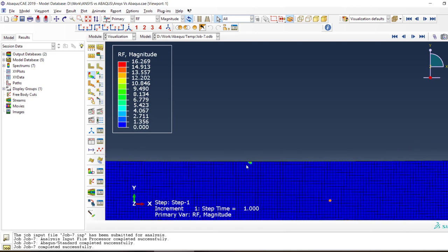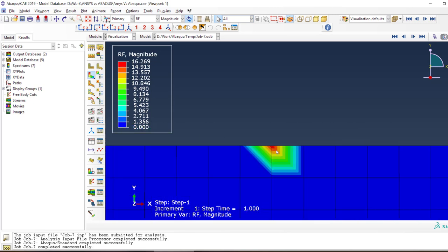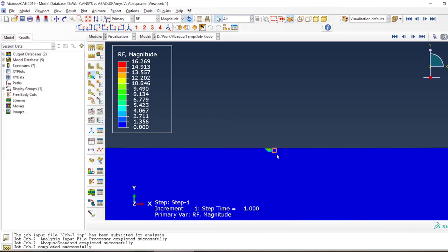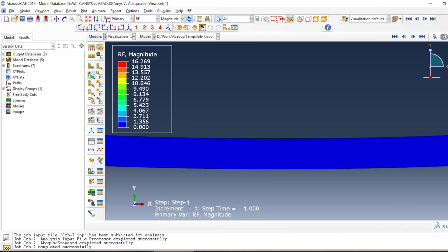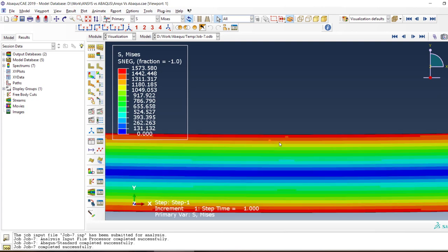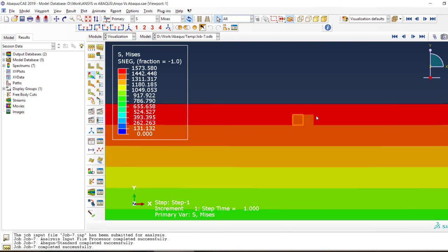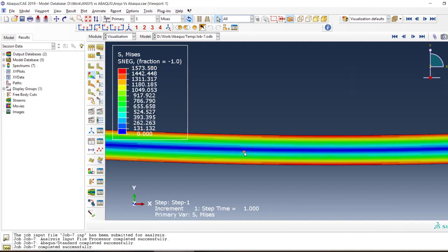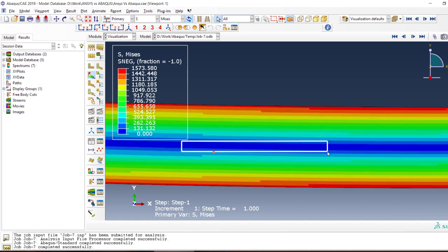So it's a very tiny element, and on the node in fact, and we can still see the feature edges, and then remove the mesh, and now we can see the stress as well. There still are two elements that are not in the band. Yeah, it's unaveraged, but it still looks good, and we can still see this region that should experience zero stress,